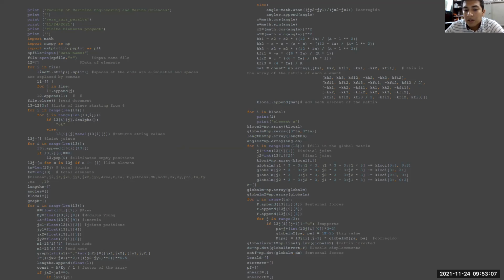The next step is that first we have to calculate the global inverse of the matrix, and we multiply to obtain the deflection. Then, with the deflection, we multiply it by the original global matrix, and we have the external force. Thank you. That's enough.